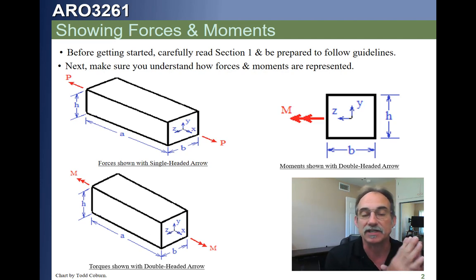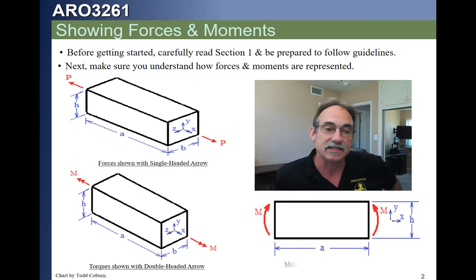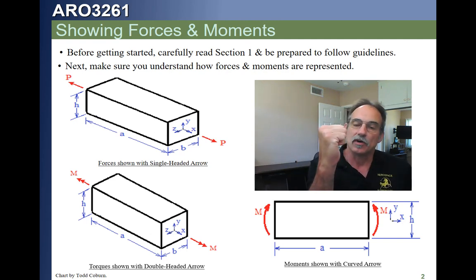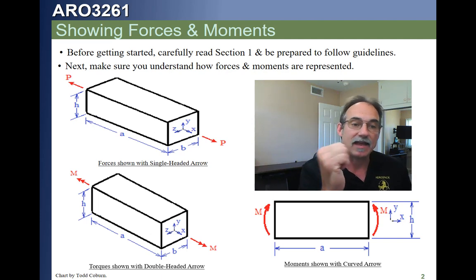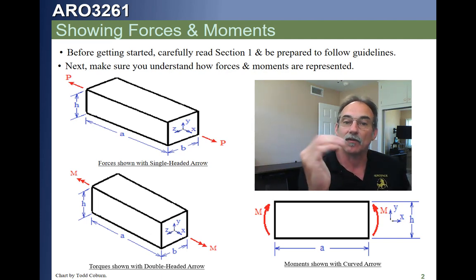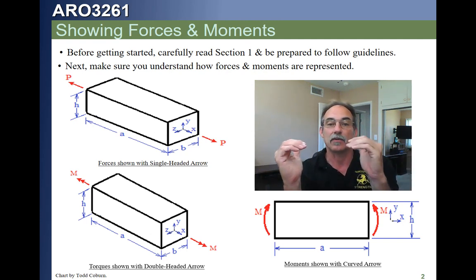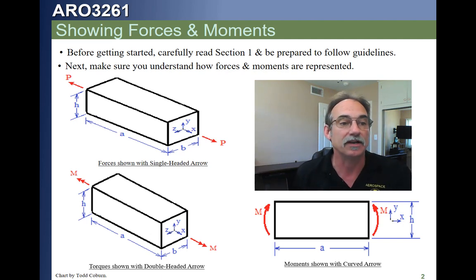Torque is just a moment, but it's a special kind of moment because it's a moment that causes torsion on the material. This is the way we often see them in statics as well. What you can see there is, if you jam your thumb in the direction of the moment, which would be coming toward my face, our fingers are wrapping on the right hand side, and then on the reaction, action-reaction pairs on the left hand side. There's our reaction, here's our applied force, or a moment. Got that? This is important to understand. This is just laying the groundwork for where we're headed.